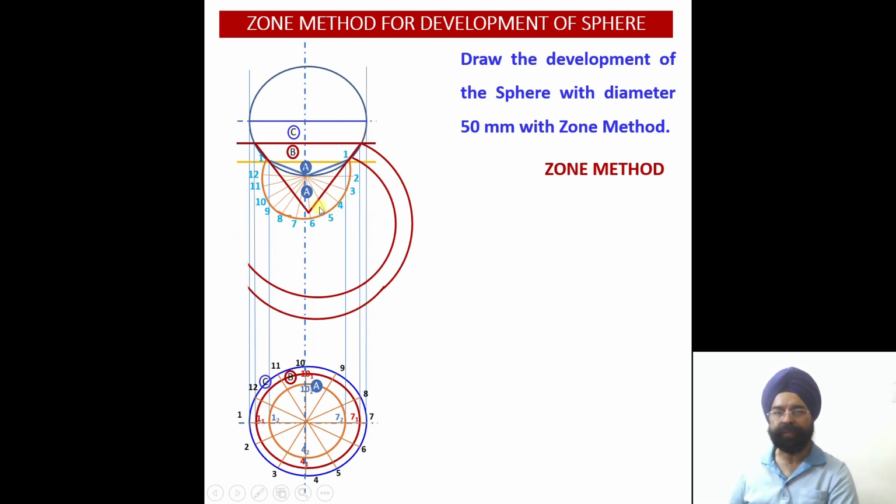Please check this out. My starting point is 1 for the second zone. This was the first zone. This is my second zone. So again, the starting point will be 1. Using this as the radius, I have drawn the arcs. Now, how much is this distance? 1 to 2, and similarly for the rest of the points, equal to this sector chord length. So corresponding to this sector, measure the distance and mark all the 12 arcs along this particular curve.